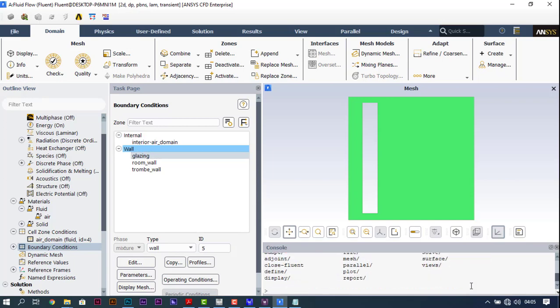So to load it, we just have to use the following command line codes: file, then read, /transient table. Okay, then we input the file name, testrad2.prof. Don't forget. Alright, so it's loaded up. So if the header file is not correct, you have problems here and your whole Fluent software will crash.